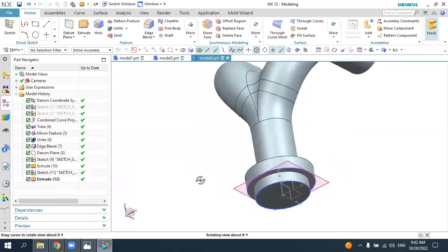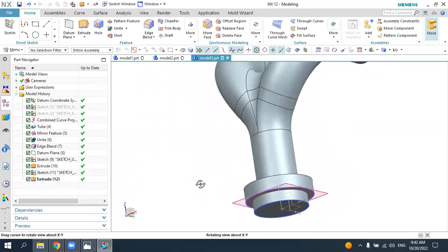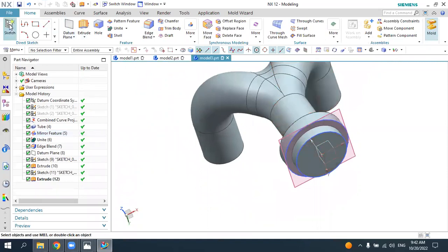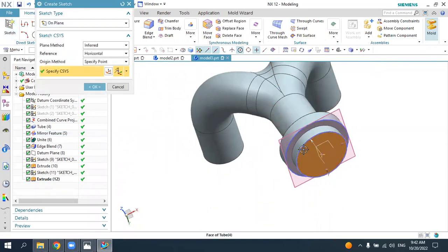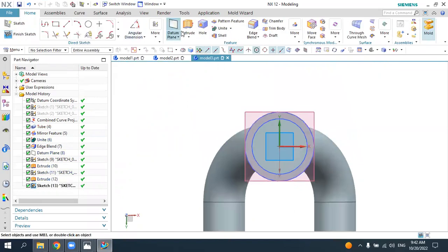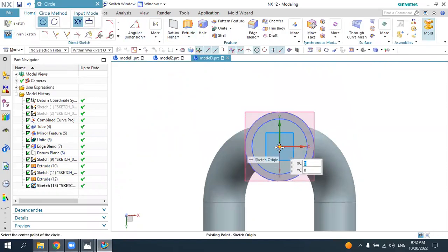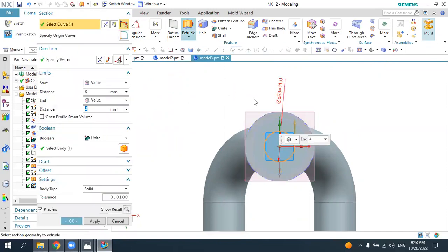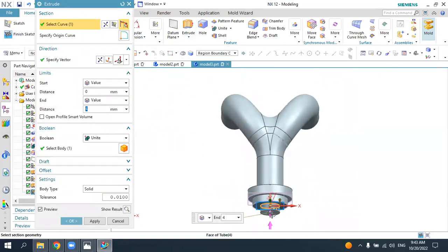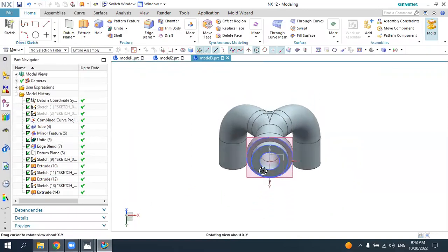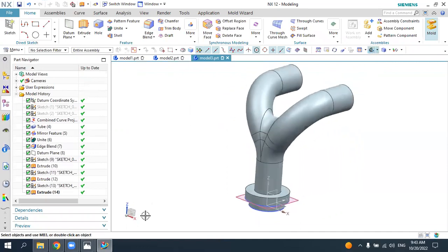So we created this one, and here we need to make the hole. The inner diameter was 11 millimeter. We need to open the hole here with the circle firstly. Make here the 11 millimeter diameter, and extrude it. Just extrude it to any position. Just make subtract. Press OK. We open the hole.